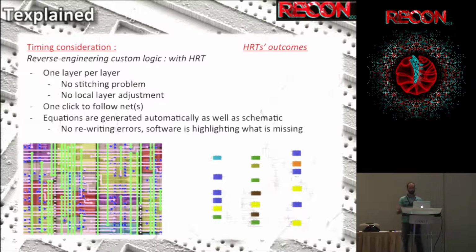And you can have errors. I mean, it's for sure, it's hard to detect millions of features of a chip without making errors. But now, as you have a netlist, you can start to look around for your errors. It's not so easy, but at least you remove most of the errors.